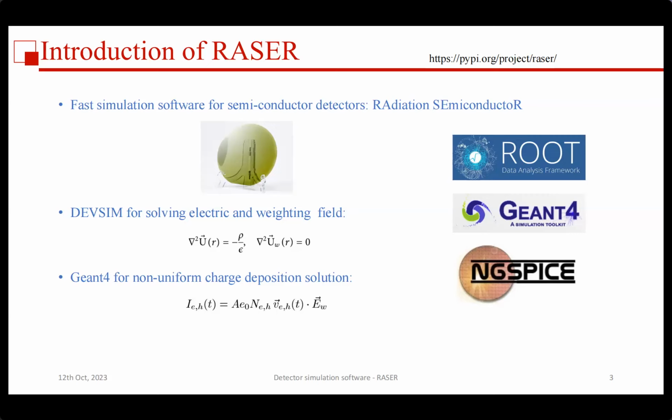We can simulate IV-CV distribution by DEVSIM, and it also allows us to get electric and weighting field distribution. Geant4 helps us to get non-uniform charge deposition. Based on the field we get from DEVSIM, we can calculate the induced current by Shockley-Ramo theorem.